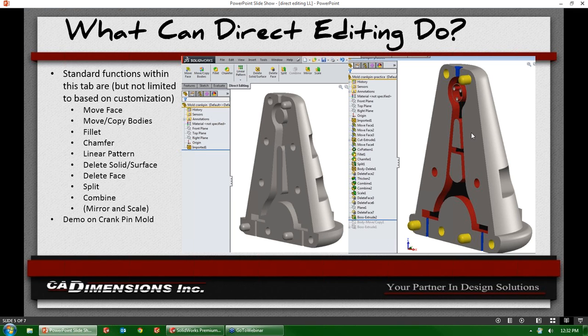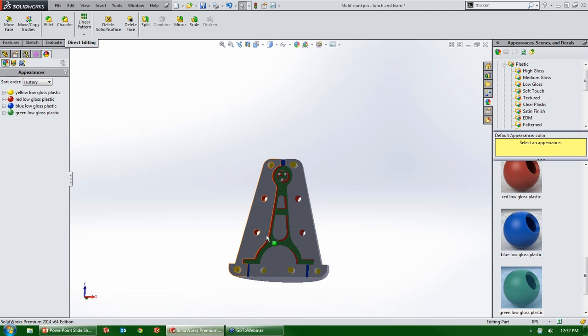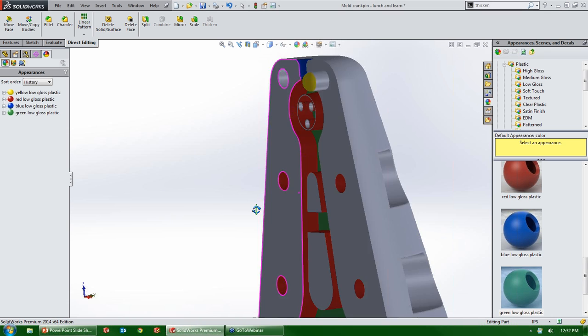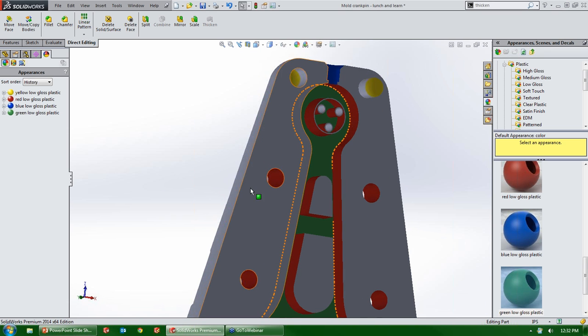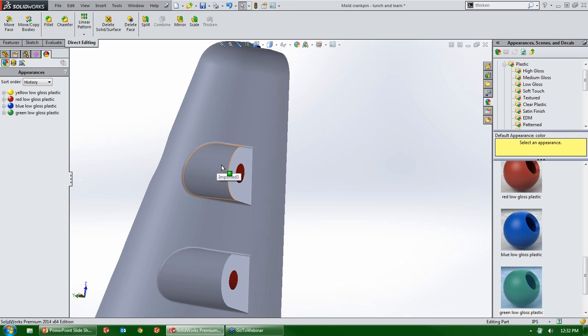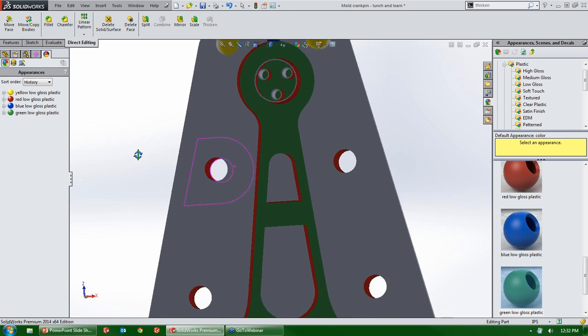The last thing I need to do is remove these through holes on the side. So because we switched over to this triple connection point internal to the mold, I really don't need these. They're not going to do anything. So why waste the support material in the printer? We'll just make it a solid. So one thing I could do is make a sketch on this surface, extrude it up to here, but it wouldn't really be as clean as what I'm about to do.